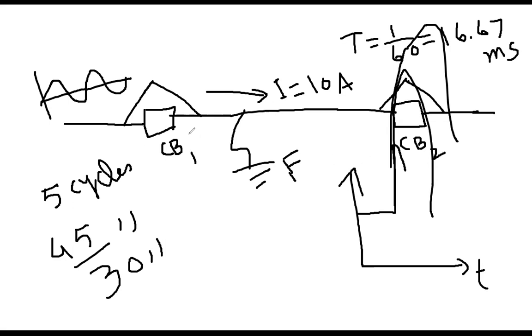So that's why it is not usual practice, when the fault is going on, which is called a permanent fault, to just close, reclose, close, reclose. It is not safe. The circuit breaker might be damaged. That's why, like in the MLGW system, I have asked them, they attempt 3 times: first reclosing, then failed, again open, again close, then failed again. So they go 3 times.